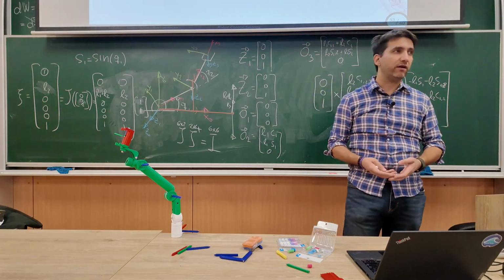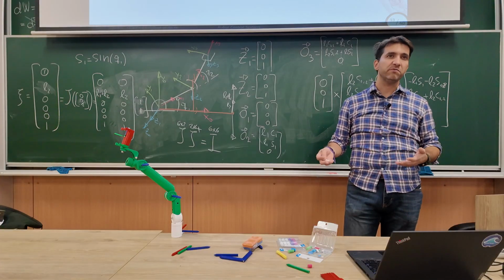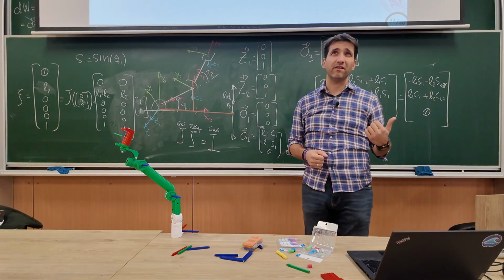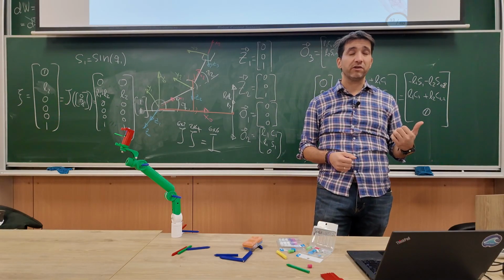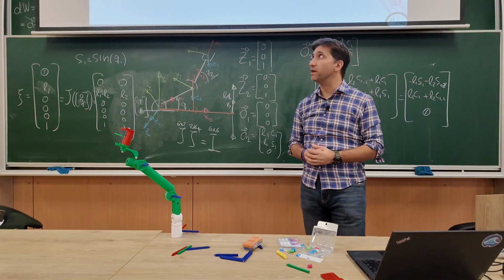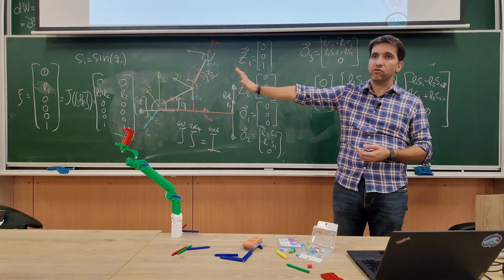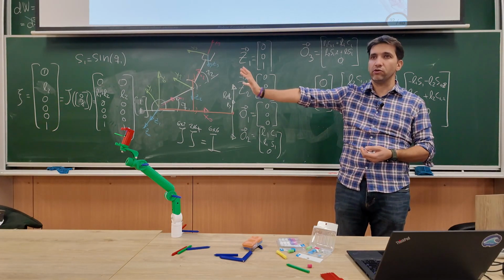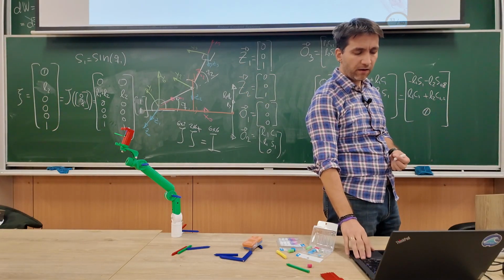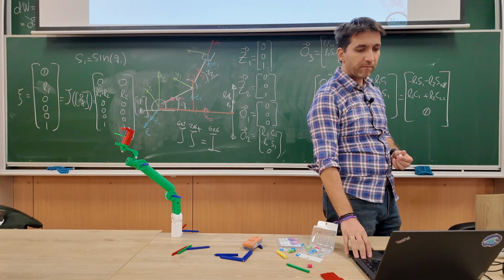They are called singularities, because they cause the Jacobian matrix to become singular, which means basically to lose rank. It's again something we discussed in the forward kinematics lecture, where we said in some configurations the robots will lose degrees of freedom, and that's what happens here. We lose a rank, so basically we are less flexible in this configuration. We don't have the flexibility to control velocity in all directions. So we lose a degree of freedom.